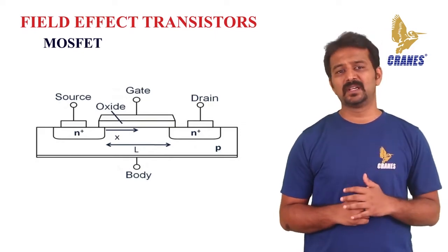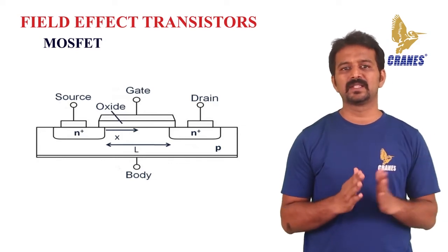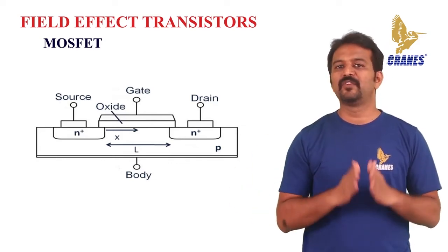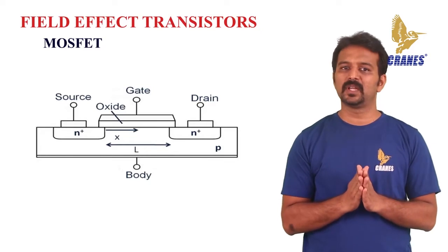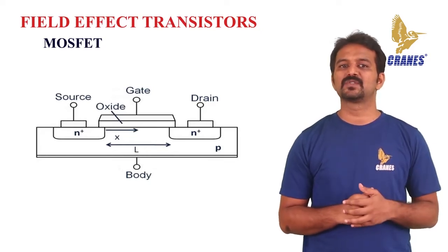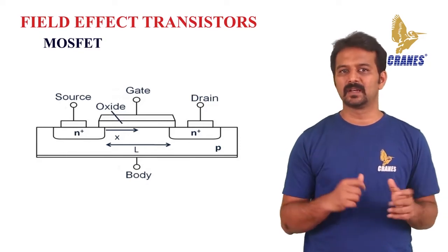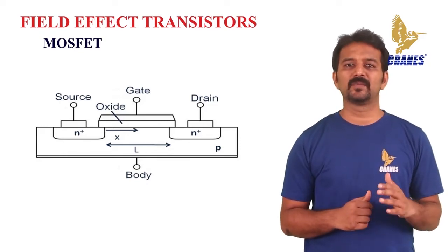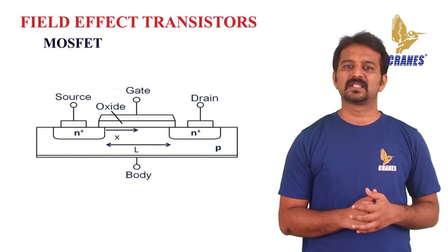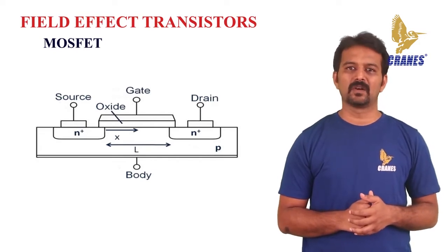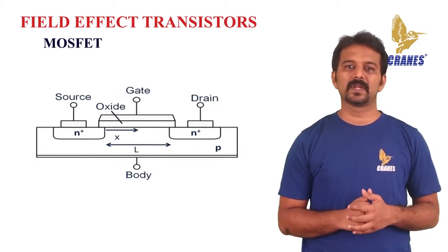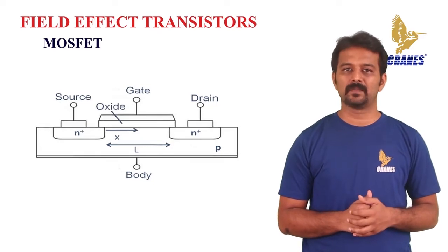The charge carriers enter the channel at the source and exit via the drain. The width of the channel is controlled by the voltage on an electrode which is called the gate, which is located between the source and the drain. It is insulated from the channel by an extremely thin layer of metal oxide. The MOS capacitance present in the device is the main part.